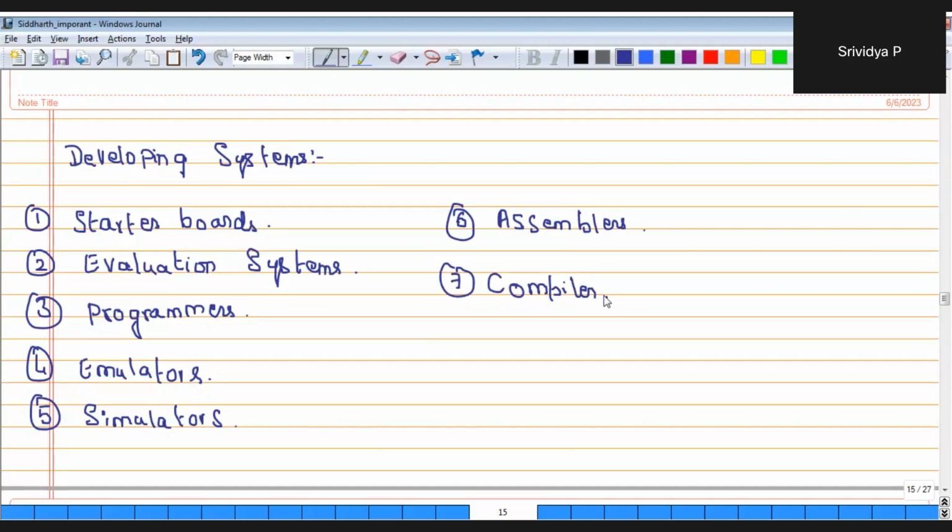Often compilers for embedded systems are called cross compilers. They are provided by microcontroller or microprocessor manufacturers themselves. Third-party tools for conversions are also available and can be made use of. And these compilers are specific to the families.